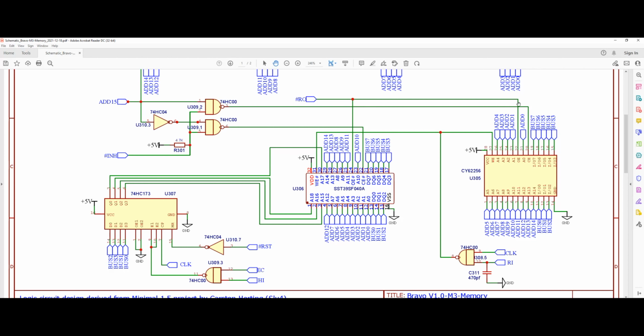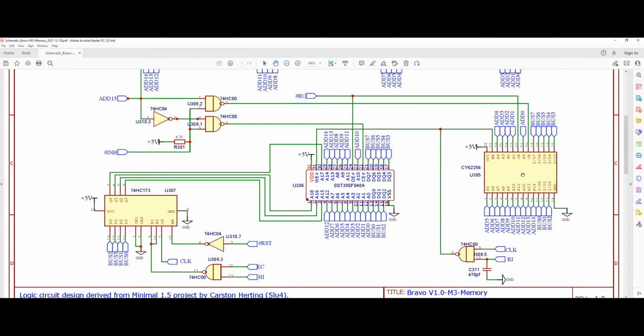As you can see, again, this is an active low signal coming to pin number 22. And whenever we bring that line low, whatever is on that memory address will be put on the bus lines, right? So I guess that is quite simple. The only difference is that the RAM out signal is an active low signal. So we need to actually bring it low, and that will output the value onto the bus.